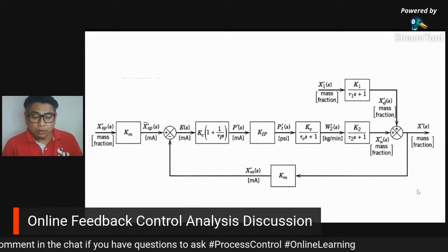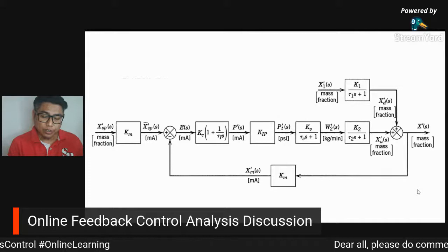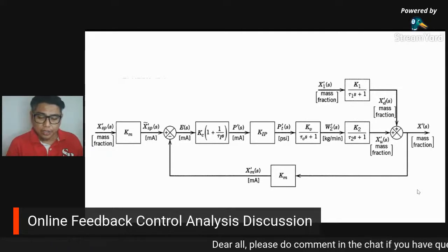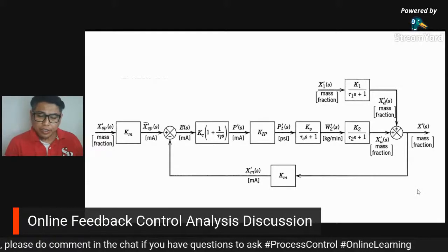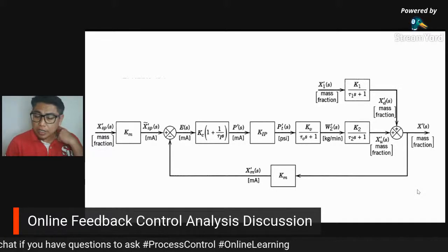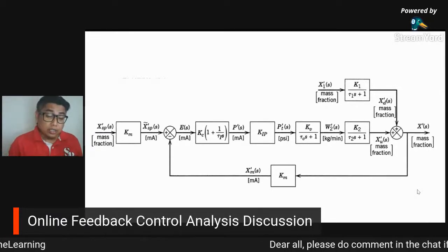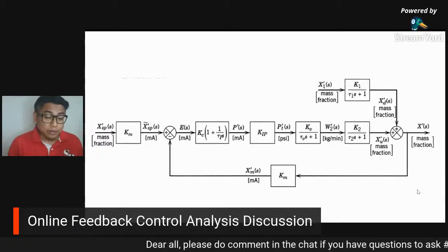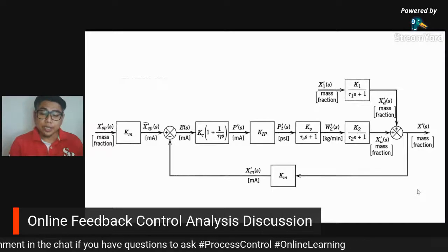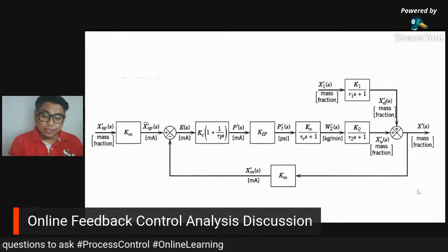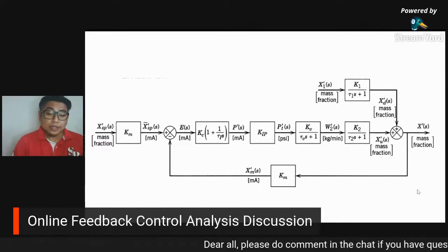All right, check all those coefficients. The first coefficient, the highest coefficient, should be positive. If it's negative, then you need to multiply all coefficients with the negative sign, and then check if there is any coefficient with a negative sign. If there is at least one coefficient that is negative, therefore you stop, because it's already unstable. If all the coefficients are positive, therefore you need to do the Routh stability criterion. Okay, the Routh array. Do the Routh array. Okay, that is basically stability.